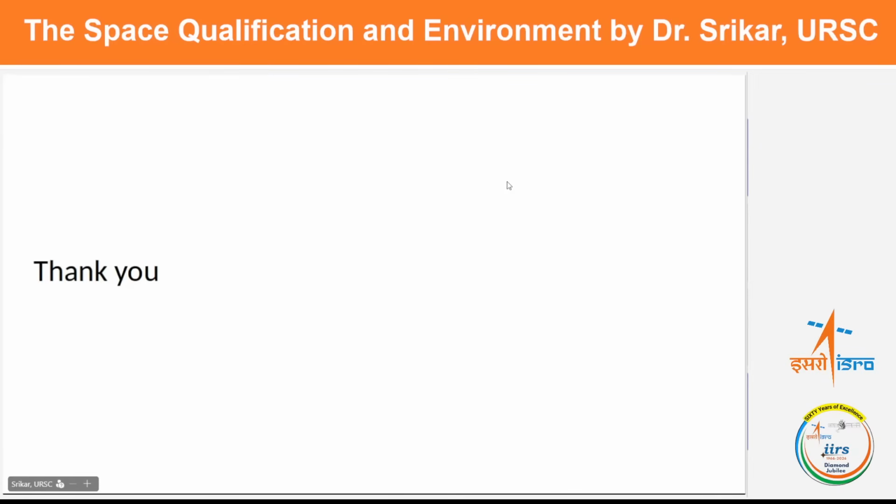Yes, because here we are looking at the launch condition. The launch happens on the ground, so we will not have the launch effects in vacuum. So when we do the testing, it is also done to emulate the same condition. So it is done in air. The thermovacuum is only for the thermal cycling and then the vacuum testing of the subsystems. Okay, thank you. Let me see the questions.